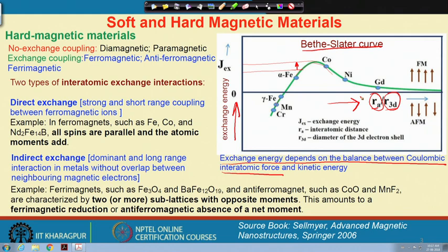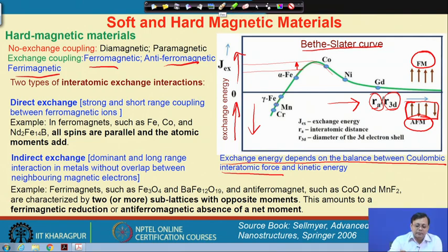Here, usually the top side is for the ferromagnetic elements and the anti-ferromagnetic part is on the bottom side. That is why the schematic is shown here with opposite sides in nature. So, for ferromagnetic, anti-ferromagnetic and ferrimagnetic materials, we can think about making some sort of exchange coupling for the benefit of making a harder magnet.